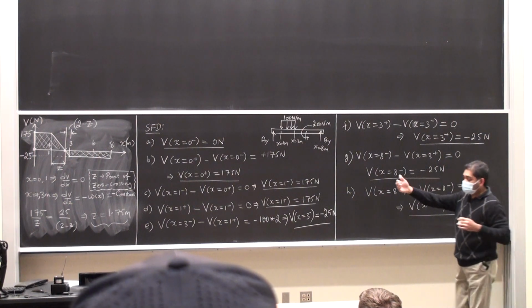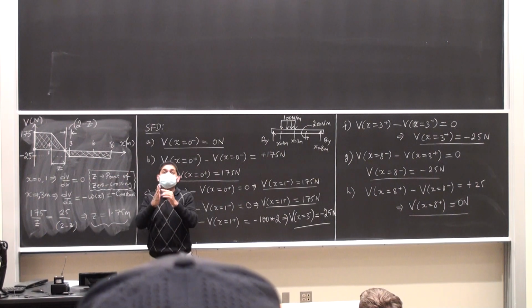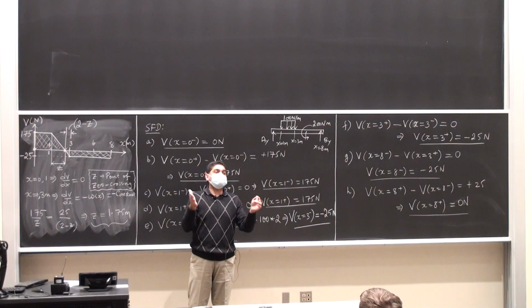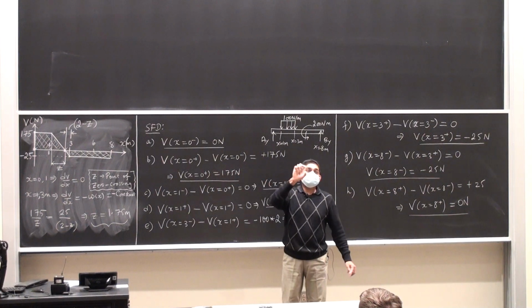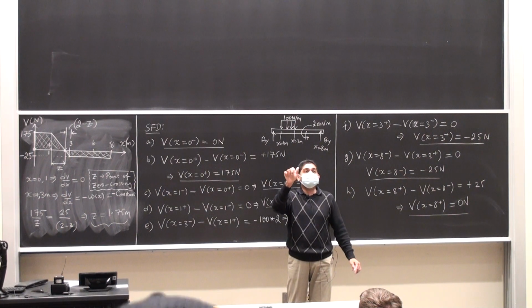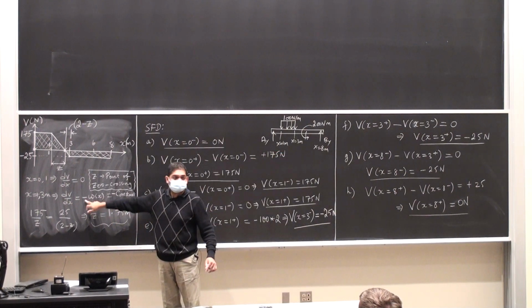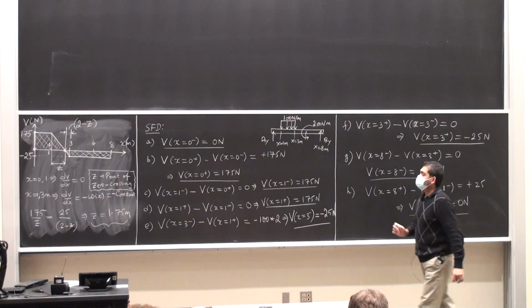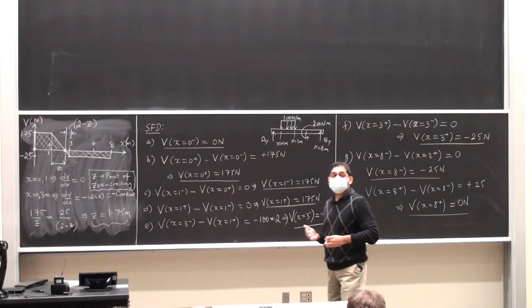Why am I drawing the line here as a straight line with zero slope? It is because the slope of the shear force diagram is equal to the load intensity value. If there is no load intensity, the slope is zero. If there is load intensity, the slope will be equal to the magnitude of the load intensity, keeping in mind that if I have a load intensity pointing down, it is accompanied by a negative sign, which means that it's a negative constant slope. It's a decreasing slope, a constant value. All right. So that being said, we are ready for the bending moment diagram.